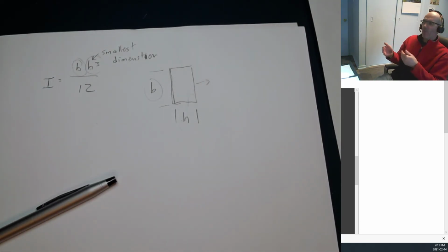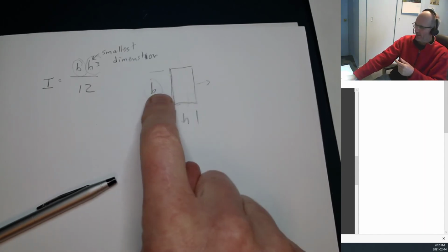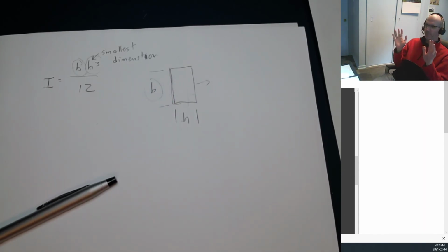If you need to make it wider, just take a look at the strength that you predict you're going to need, and then take a look at the strength that you've measured, that you've calculated, and it's just a linear ratio. You need something twice as strong, double the width. Okay, that's about all there is.